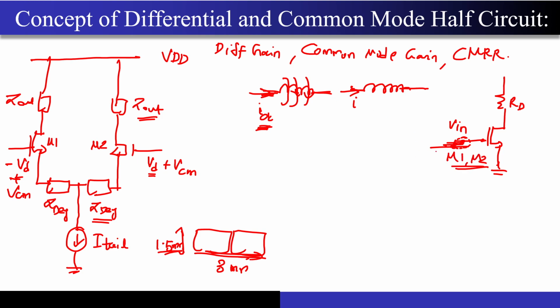Correct. Now the purpose of telling you this is there is a time varying magnetic field that is getting generated over here, and there is a conductor that I have just placed over here. So now what happens? Let's say this is a conductor that I am placing, and there is a time varying magnetic field going on. So this conductor is sitting in a time varying magnetic field. And you know from your class 12 physics, right? There will be a voltage that will be generated at this particular net. Now this is noise, this is interference, I don't want to amplify it. So what is the best way